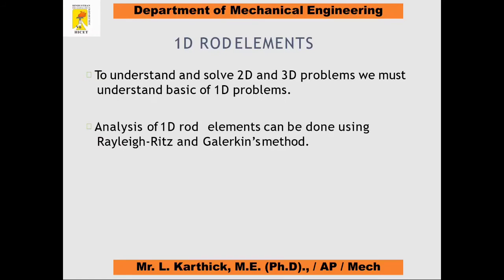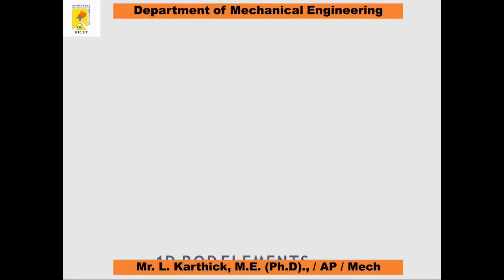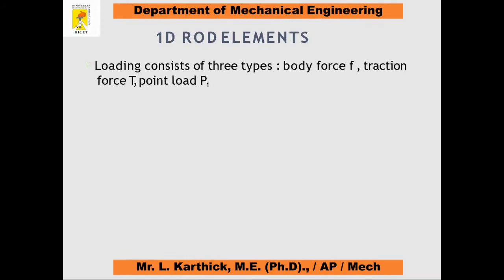Analysis of one-dimensional rod elements can be done by using these techniques, the Rayleigh-Ritz method as well as the Galerkin technique, to find or create an expression for the deformation or displacement. To solve finite element analysis problems, these are modified into the potential energy approach as well as the Galerkin approach. It is similar to the Rayleigh-Ritz method and the Galerkin method. So we also apply this with the potential energy approach as well as the Galerkin approach. Then we need to find the displacement, stress and strain for each and every structure.